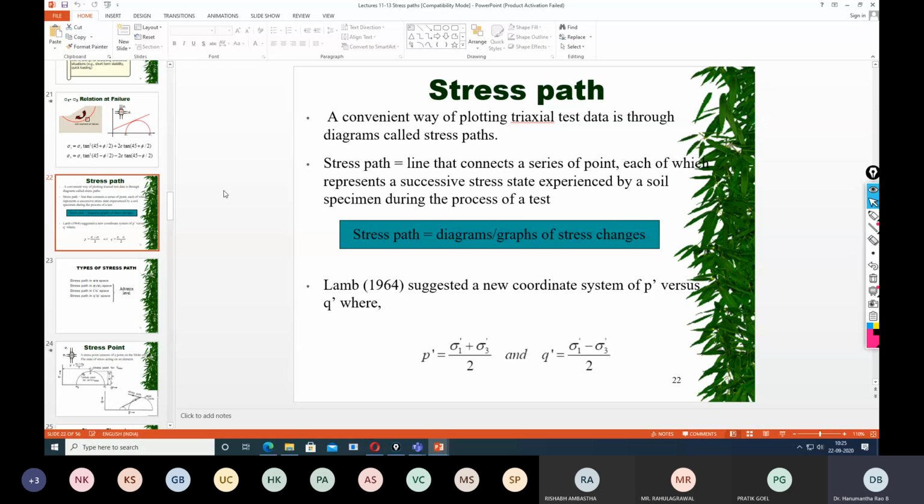But you have to understand one thing. When I talk about all these things, you should earmark two areas. One is right below the superstructure, one is right adjacent to the superstructure. Whatever I said is valid only right beneath the superstructure. But what will happen right adjacent to the superstructure, where there was no delta sigma at all? There the soil undergoes this entire cyclic process: CU, CD, CU, CD, CU, CD.